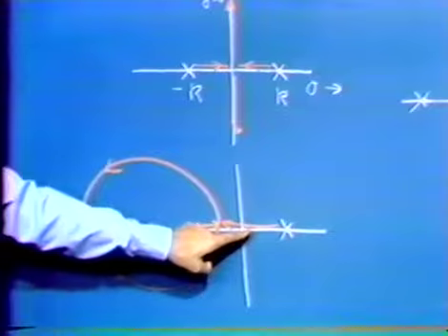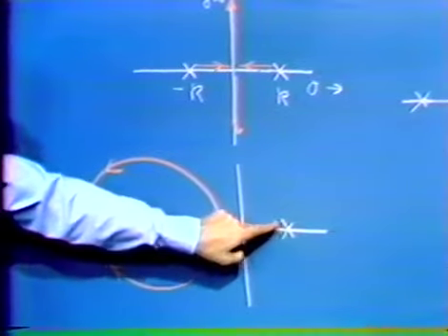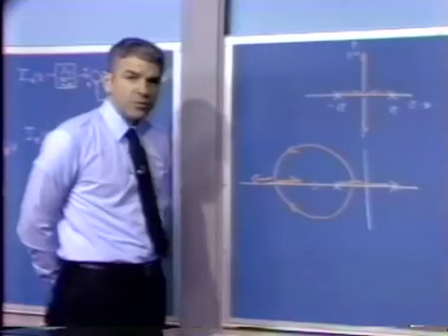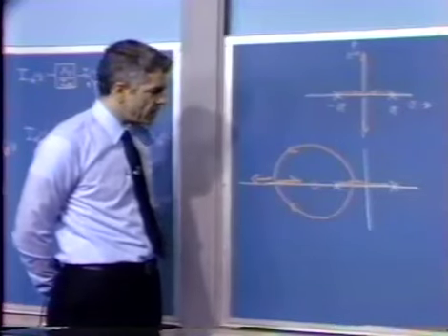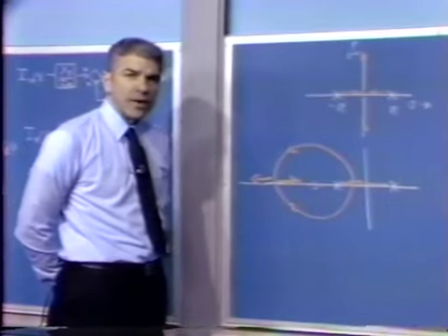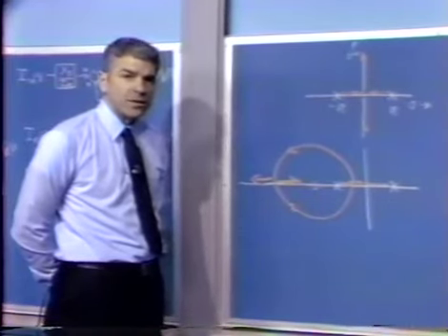And so once again, for sufficiently large values of A0, we'd have this branch in the left half plane. We'd have both of our closed loop poles lying in the left half of the S-plane. So adding a zero combined with a sufficiently large magnitude for A0 is certainly one way to stabilize this system.